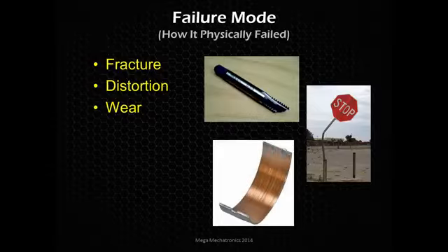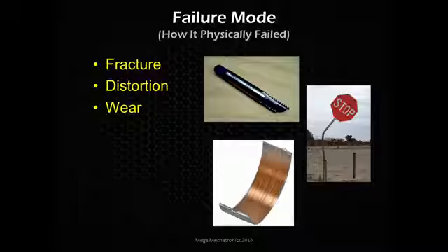Wear can cause lots of problems and lead to catastrophic failures or even fractures. So this is a bearing that's probably from an engine. When a rod bearing blows out, then you start heating up your crankshaft and you can even break your crankshaft from the excessive heat, and that's ruining your heat treat and fatigue protection.